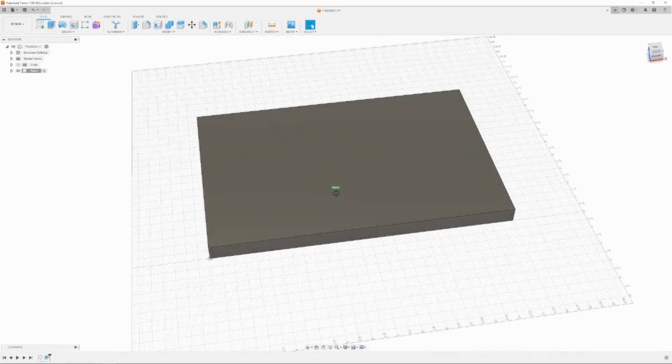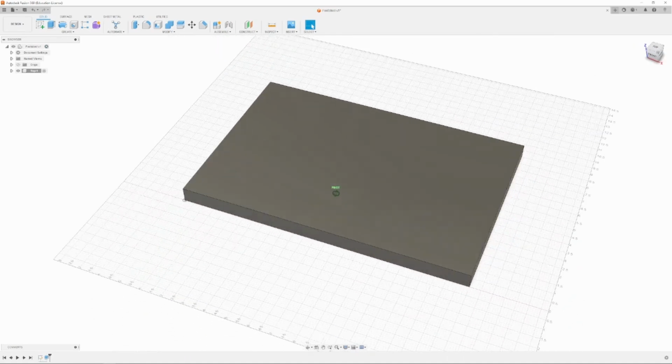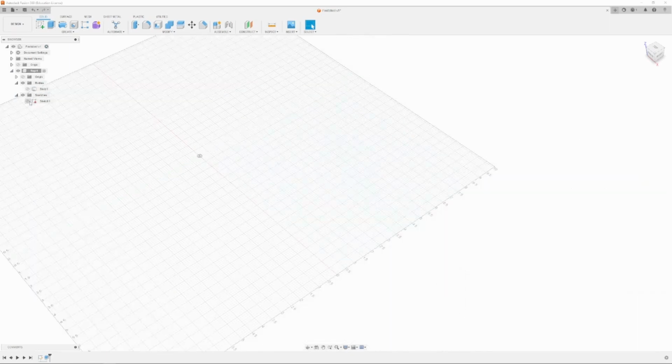But hold on, maybe if you've seen the footstools, you know that they have a hole in the middle that's a handle. So we are going to draw that next. So I am going to start a new sketch. We're still in the top component, and if I do this drop down, I can see the different things. We just created this body, that's the 3D part, and the sketch is the two-dimensional part that is just the drawing that we based it off of. So I can leave those like that, and then I'm going to start a new sketch.